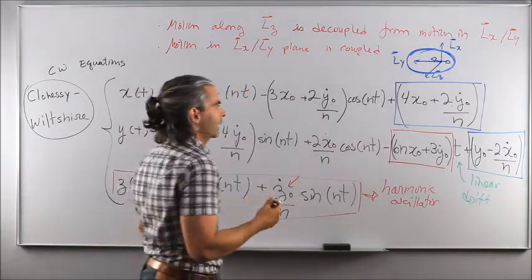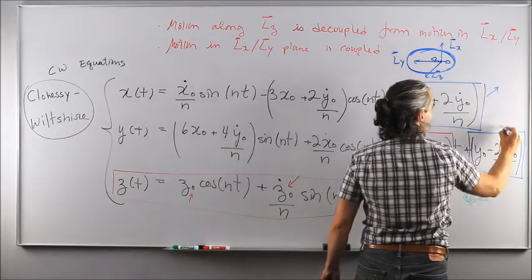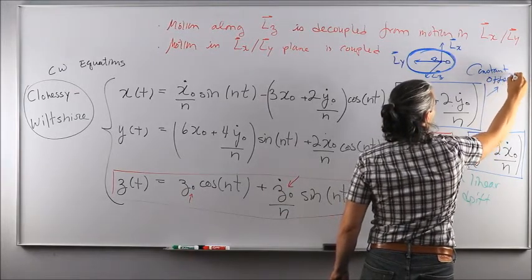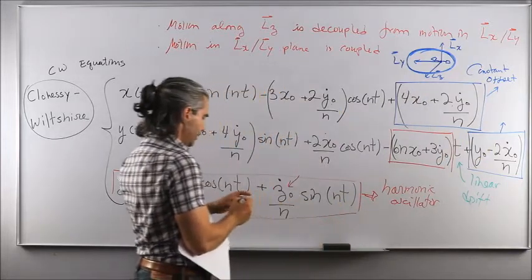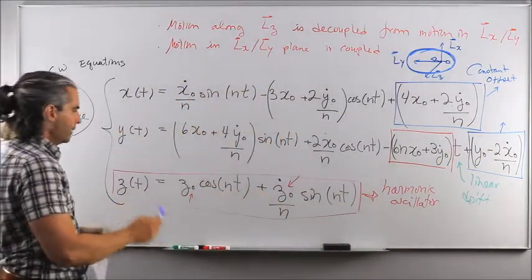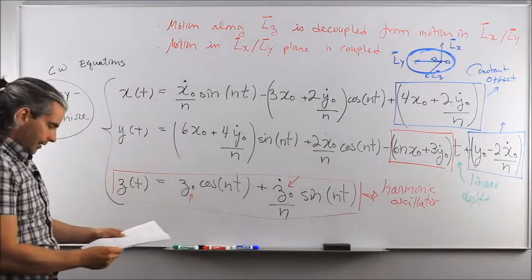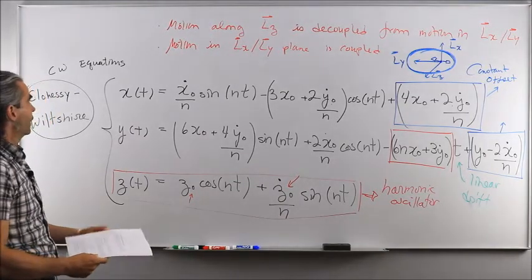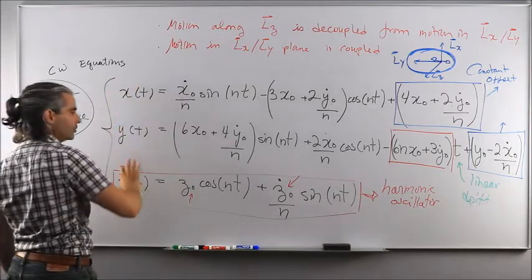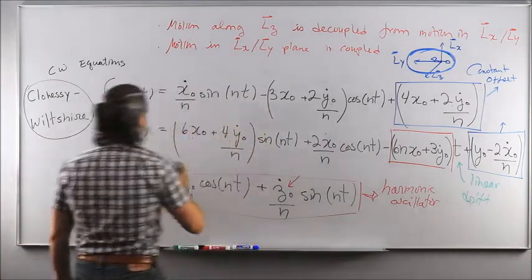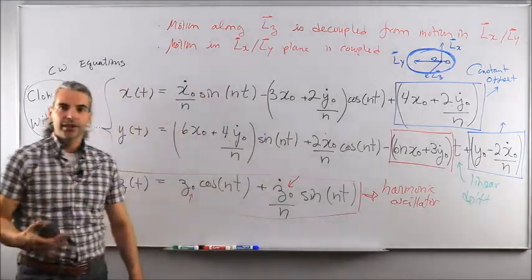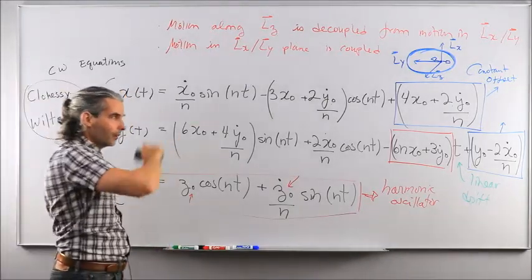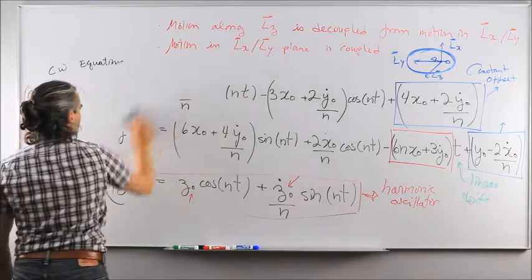So in practice, people like to also cancel those two terms, which is just a constant offset of the relative motion seen in LVLH. Okay? So I think that this is what we can conclude for now in terms of the closed form solutions to Hill's equations. Okay? And again, everything we just said here is under the assumption that x, y, z are small compared to RT, and that the target spacecraft evolves along a circular orbit.